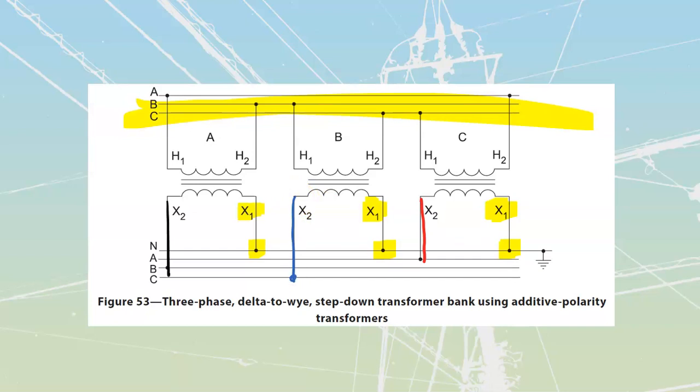Okay, it is the most confusing one for us to go and have to draw, just because of the fact that we have got the C phase transformer that is feeding the A line. But as far as the actual vector addition goes, this whole thing does add up, and it works well. We get a proper 3-phase system that does proper 3-phase things.